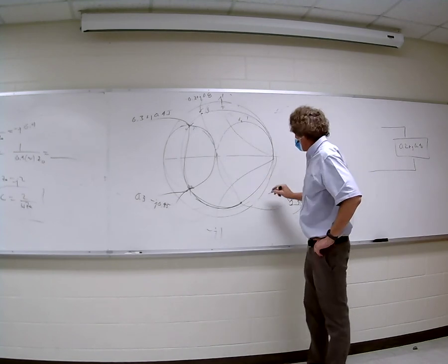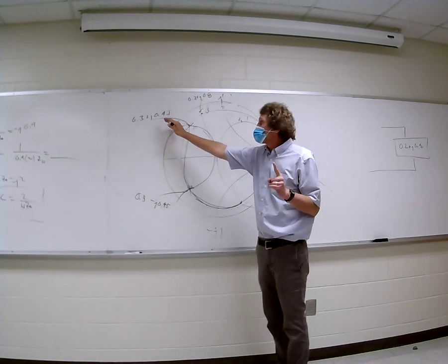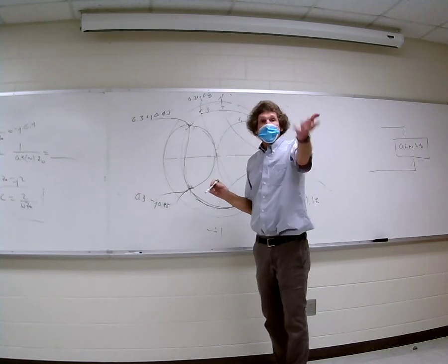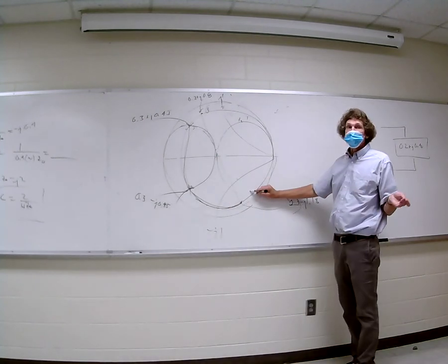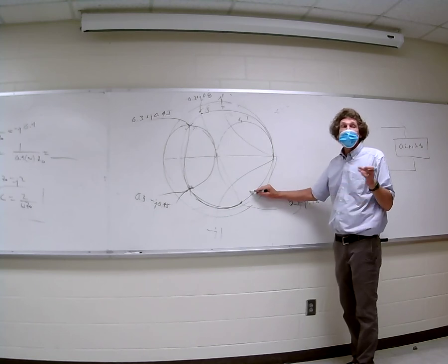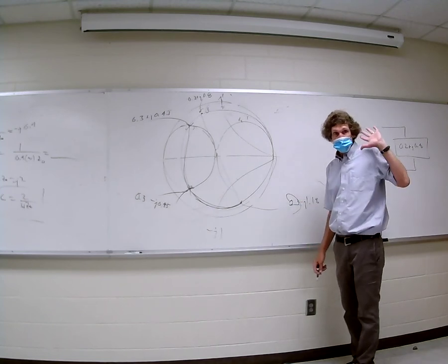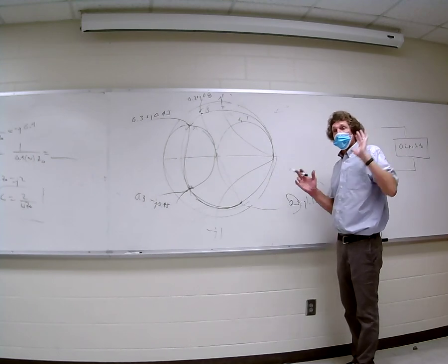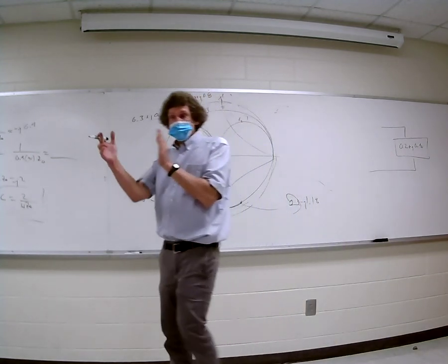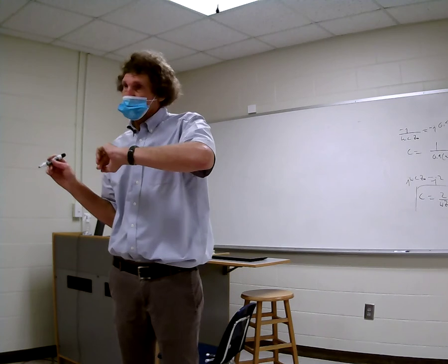So what do we do? We move from here all the way to here, because now we have 0.3 plus j 0.45. You agree? Take 1 over that, and now we get a negative value. We get 1 minus j something, right? Follow me? And it's in series, so I can add an inductor to get rid of that negative j business. Do y'all follow me on this, class? Lydia, with me? So remember, we want inductors in series, capacitors in parallel, and nothing in between. And that's the moral of the story.